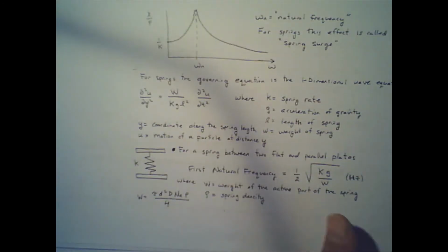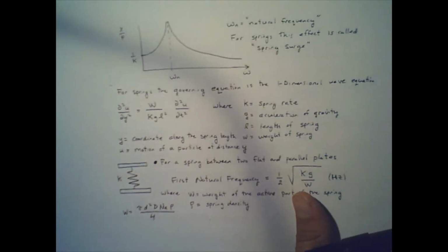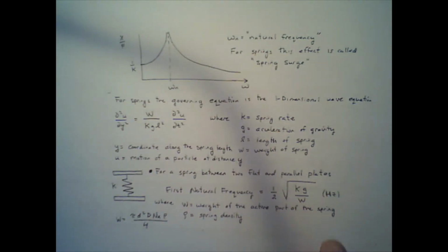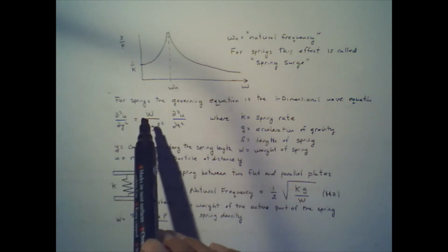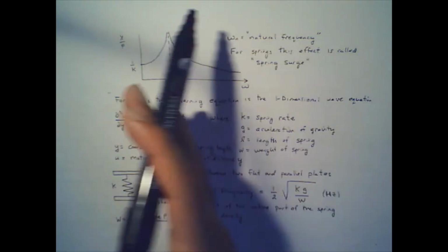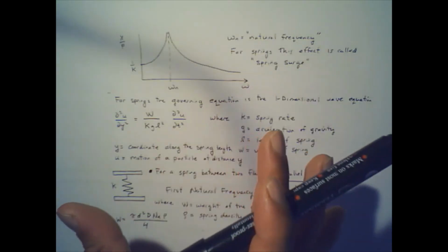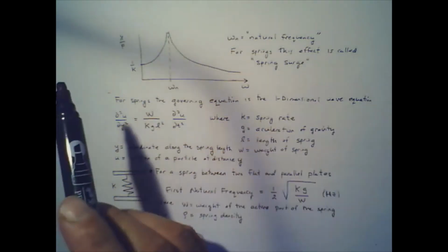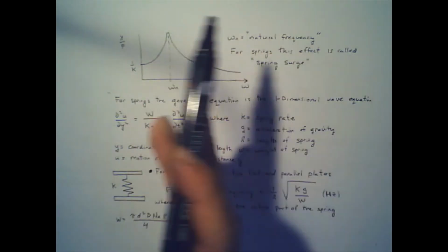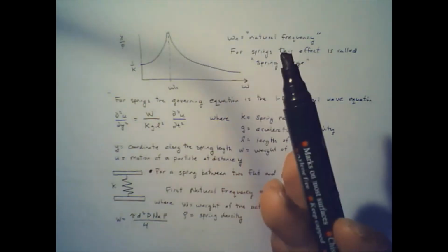Lastly, regarding springs, I would like to go over the natural frequency of a spring. Here you don't really need to go over the wave equation of a spring, because you have some density that fluctuates. The coil itself results in natural frequencies, and inside the spring some coils will actually vibrate as well, so the spring itself will have mode shapes.